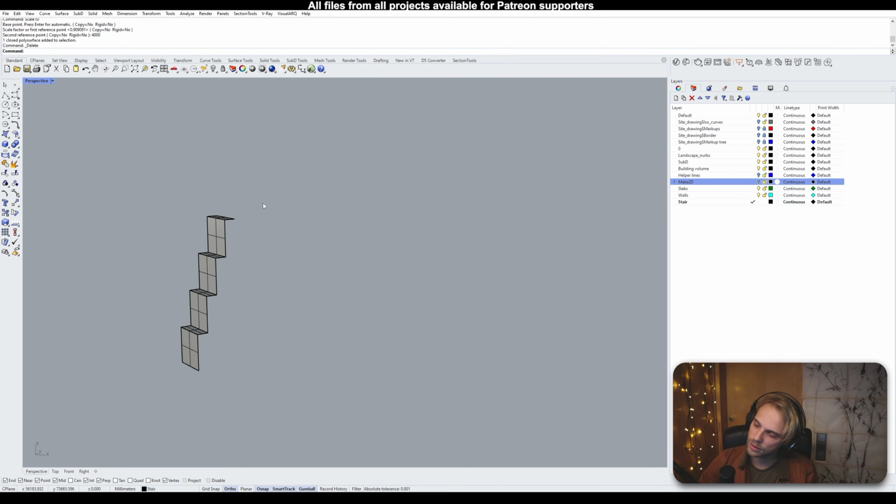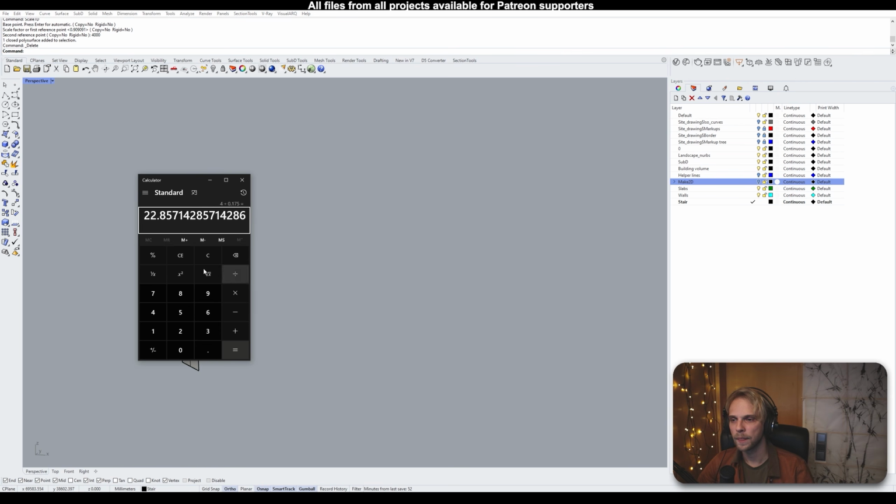So you don't anchor yourself to a typical step size for a stair, 0.175 meters, 175 millimeters. No, you don't do that. You instead do quick math, calculate approximately how many steps you would need, 4 divided by 0.175.